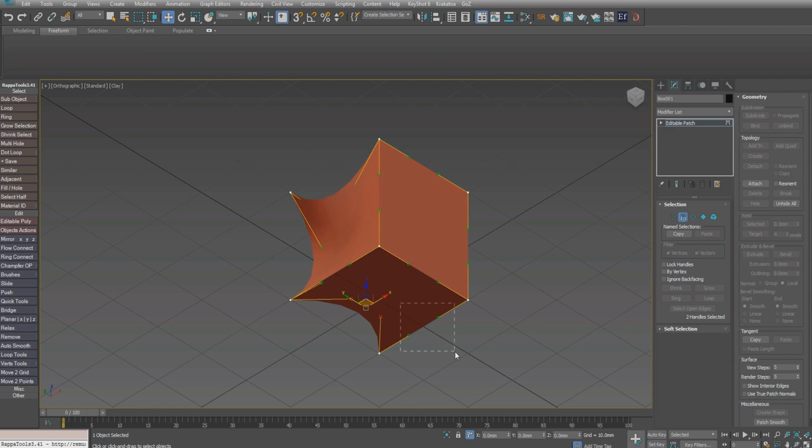Okay, so around we go here on the outside of the object. And we'll come back to the Z parameter this time. And again, we'll enter a +7 as our value and hit enter. And keep going around the outside of the object. This time on the Y parameter, we'll change that to, again, a +7.